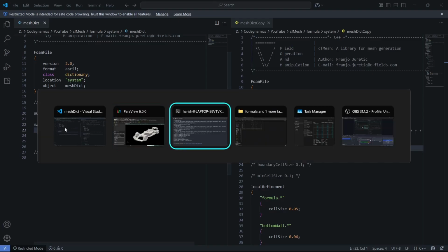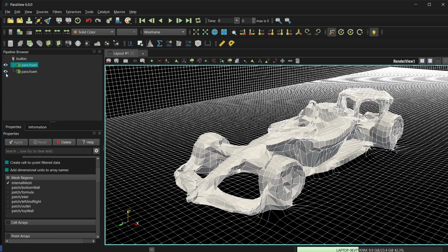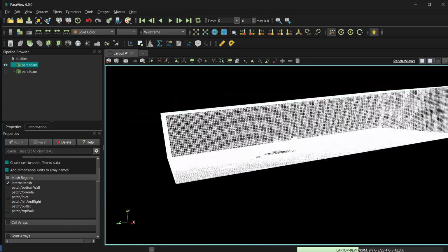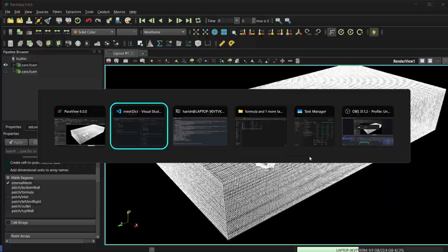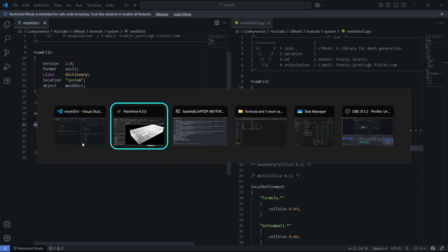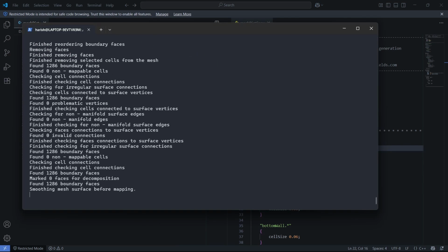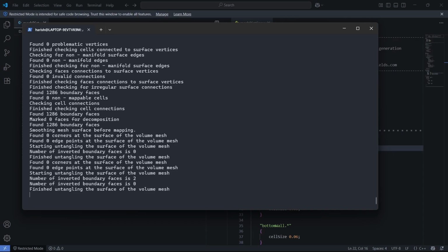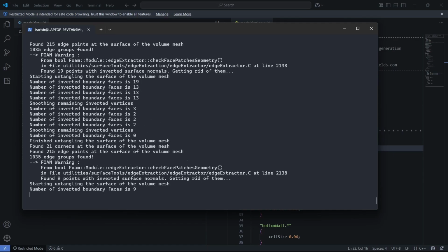But you also have a lot of cells now in the overall domain. It gets smaller and smaller. Even in the region where there is a free stream, you have a lot of cells. So what we are going to do is keep this as 0.7 only, save it, and then run the cartesianMesh again, just to understand what the size of the mesh is going to be.